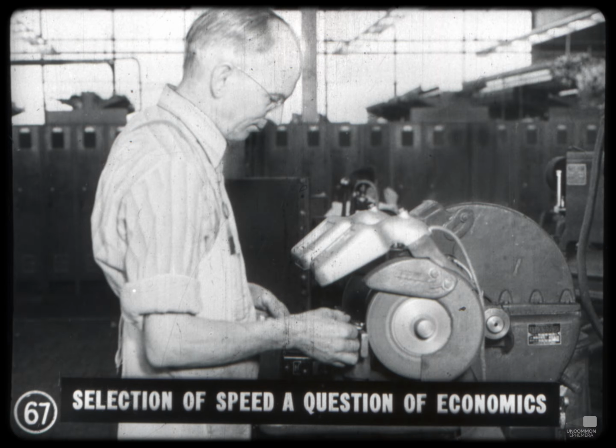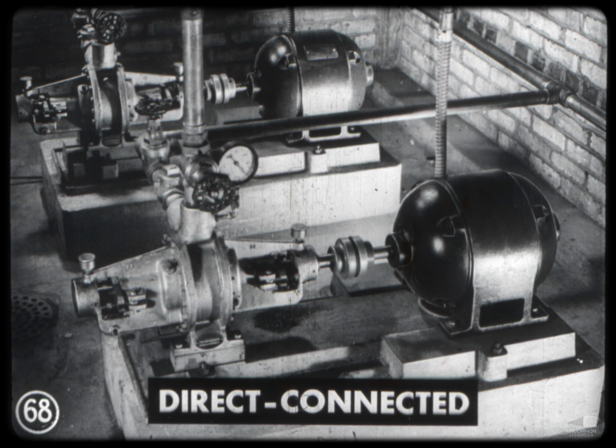When a machinery manufacturer chooses a motor, selection of the proper speed often hinges on a question of overall economics for both motor and machine, particularly on grinders, pumps, fans, and other machines which run at constant speed. On a pump, for instance, which runs at a constant speed of 1,800 revolutions per minute, a direct connected 1,800 RPM motor can be used, thus greatly simplifying the drive.